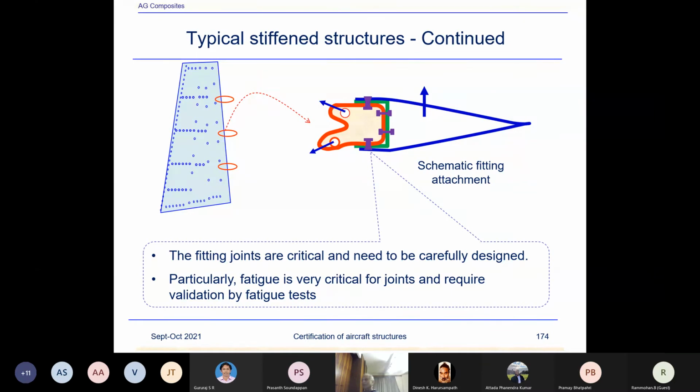We control it, as I said, with the material specifications. They manufacture the material as per the specifications, and then they have to meet the conformance requirement. They have to provide a conformance certificate, and when the industry receives the material, they make a few tests to see whether the material which comes in-house meets the requirement.